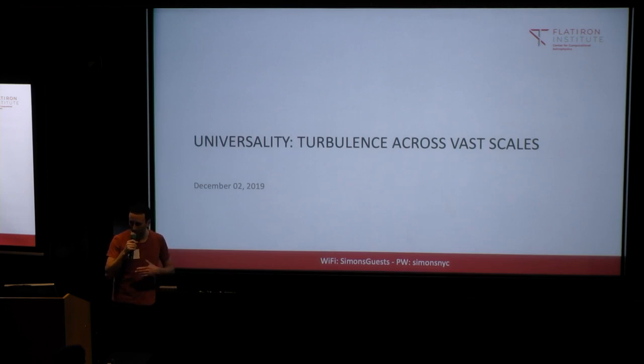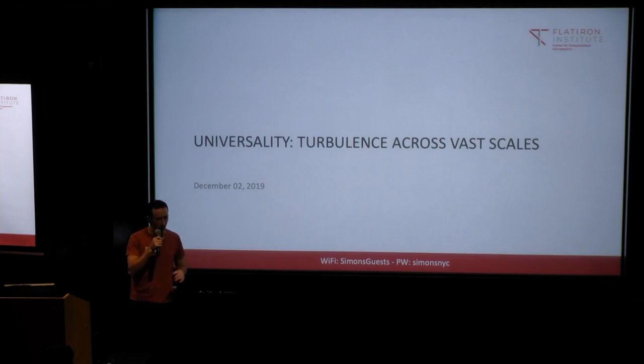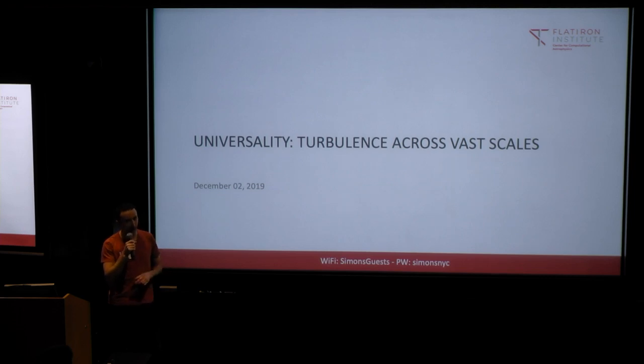But the idea is that this elasticity can alter the route to turbulence. So instead of being just driven by inertia, like in regular hydrodynamics, you can also have purely elastic instability mechanisms, and purely elastic turbulence, where inertia is not playing any role. And on the other end of the spectrum, when you have a little bit of elasticity, it has been known for a while that elasticity can stabilize some of the inertial instabilities. Those two limits have been known for a while.